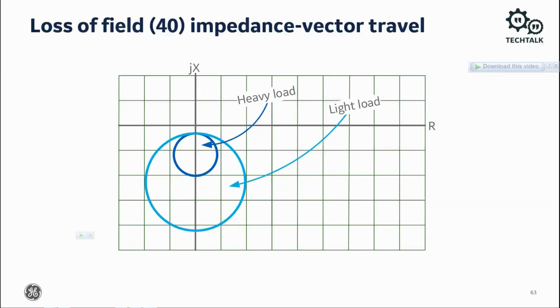All impedance settings refer to the relay side impedance quantity, which is the CT-VT secondary side when looking into the machine. Although the setting values are in positive ohms, this protection function is looking into the generator, and hence the circle characteristics are shown reversed.